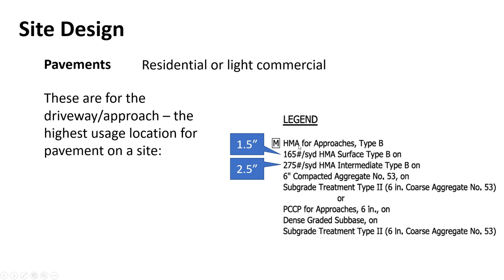All right, so it works together as a piece, and that's 10 inches total of active depth. I guess that's how much you'd have to excavate before you put this in, right? 10 inches down at least for that. And in the concrete, same story. You've got 6 inches, but you also want to do either a dense graded subgrade, or you're going to do a subgrade treatment, which sometimes is just throwing more aggregate in, right? So that's quite a bit of aggregate.